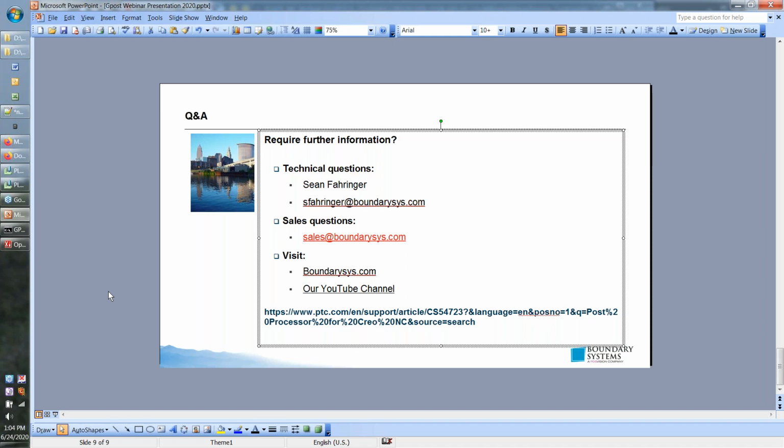We typically just write a post as necessary for what is necessary. I don't typically go get something from the PTC library myself. So, while I can show what's there on the list, I can't speak to its quality, its level of completion, current state, any of that. And the last I knew, PTC does not directly support those posts. They are available. You can go download them. You can use it as a starting point, but they don't know anything about it if you call support and start questioning what's going on with that post.